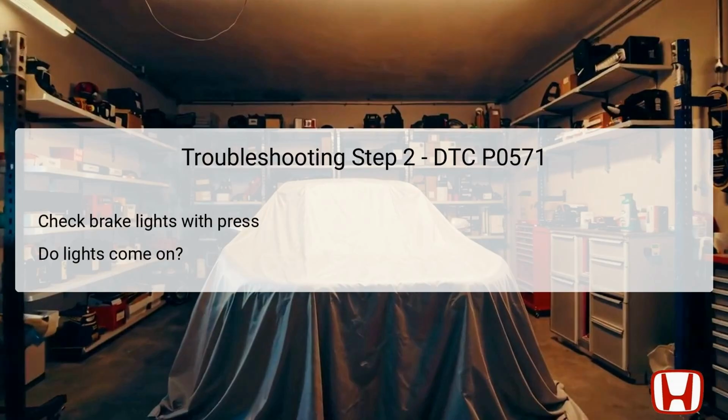In the second step, the brake lights are checked while pressing the brake pedal. This step is crucial for assessing whether the brake pedal position switch operates correctly when activated. If the brake lights illuminate when the pedal is pressed, it indicates that the switch is functioning correctly in terms of signaling the lights.